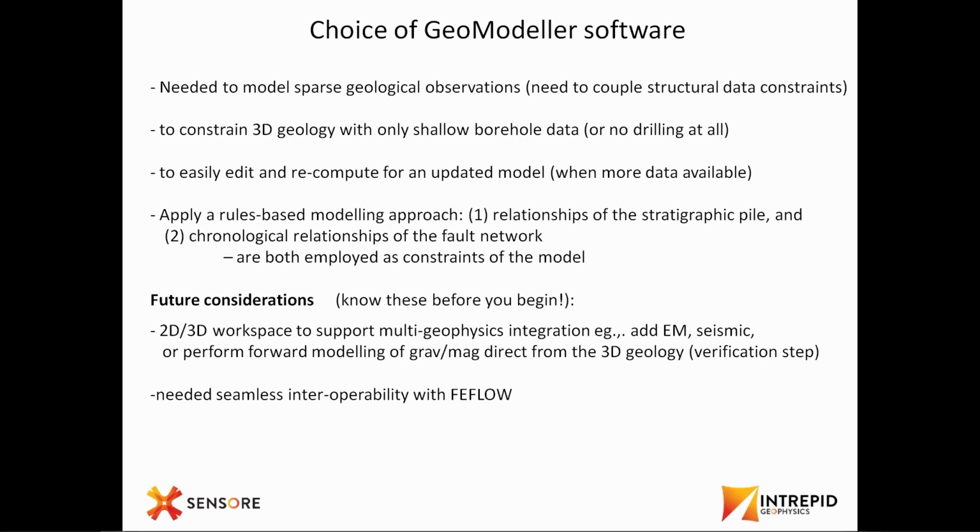Since GeoModeler understands the data, stratigraphy, and the orientation properly, it will use all this information and try to calculate the interpolated surface based on co-kriging interpolation, which is the best geostatistical interpolation algorithm.